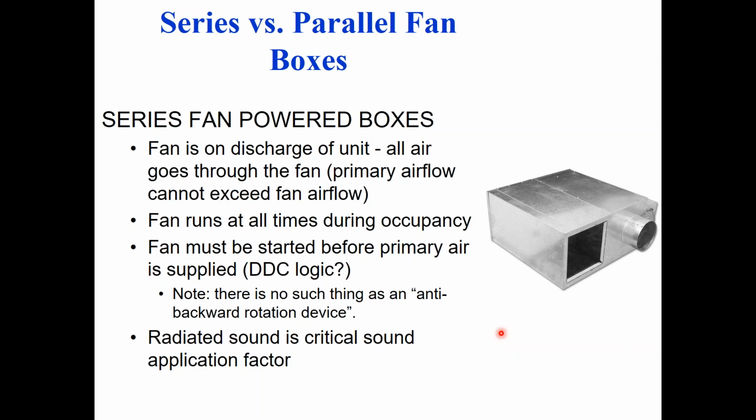Now, when you start up a series fan power box, the box's fan has to start before the air handler starts. I'm going to repeat that. The series fan powered box's fan has to turn on first, and then a minute or two later, the air handler is allowed to turn on. If you don't have DDC controls, it's very difficult to coordinate that. Basically, you have to put a bunch of schedules on your individual zones, if they even have schedulable stats at that point, and tell them to start at, I don't know, 6:45 a.m., and then tell your air handler to start at 6:50 a.m. or something of that nature.